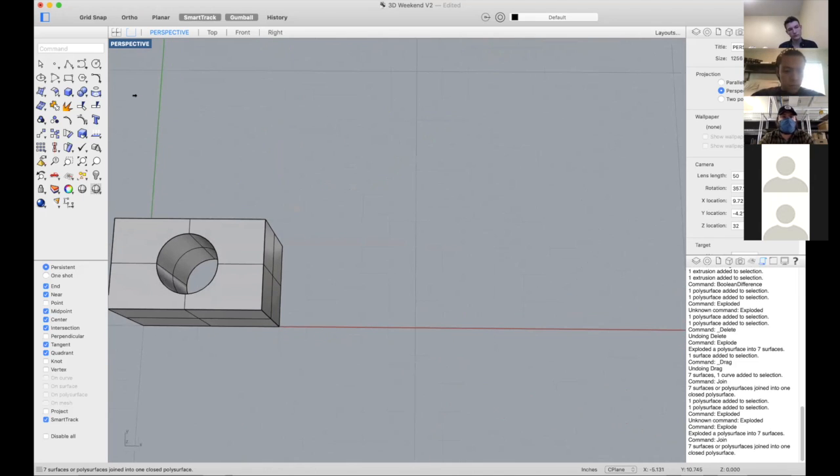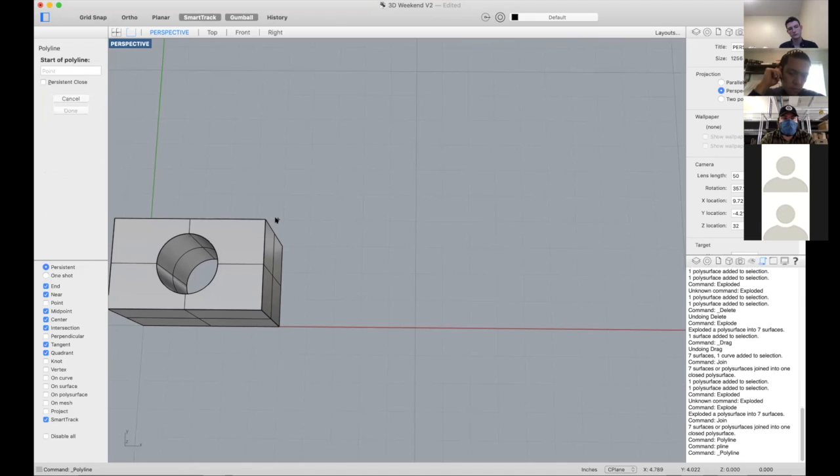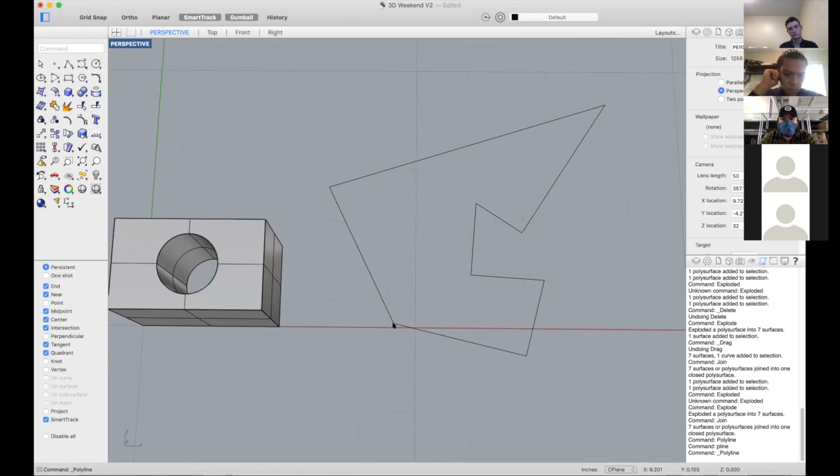Next thing we're going to talk about is compound shapes. So you can make any number of compound shapes for extruding or revolving. One of those ways to do that is with polylines, which is this button here. You can also just type pline, or you can type polyline. Again, it's just shorthand. Pline is pretty easy to remember, and if you do it a lot, it's just PL, and then it comes up. So let's say we want to start it here. You can make any sort of compound shape with right angles, or with just angular angles, and close it.